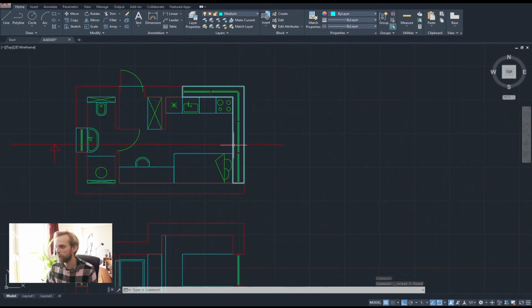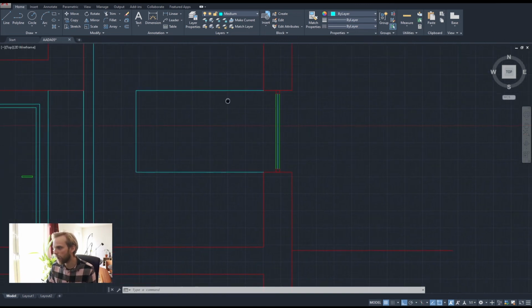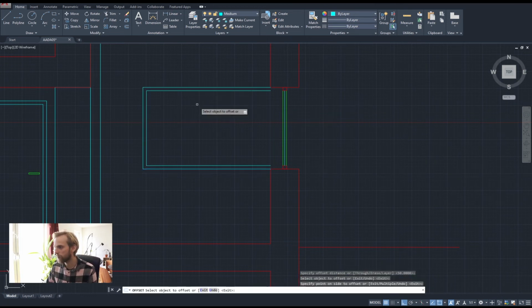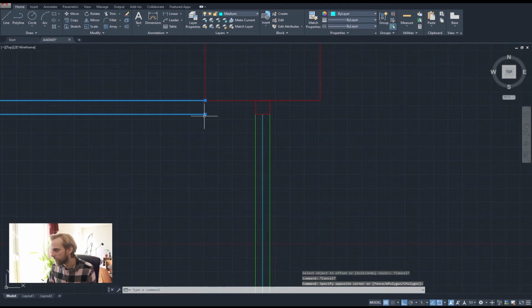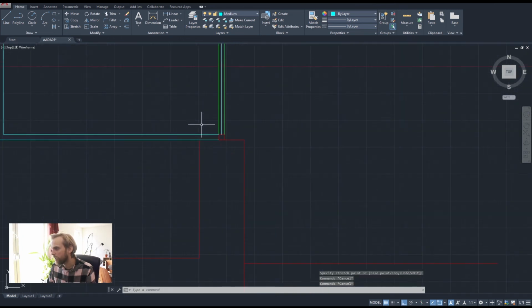Because as I'm looking through this, I never see the, here I see the wall, here I won't see the wall, right? Because I'm looking through it. I have a window that goes through the whole facade. So that's done. Now I will offset 50 millimeters. I will offset this by 50 millimeters like that. And I will actually extend it just by grabbing the control points. Or you can use extend tool, that's fine as well. I'll extend it until this window.